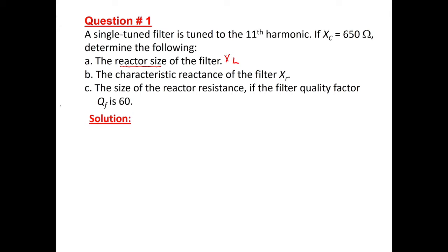We know XC, we know H, therefore XL is equal to XC divided by the harmonic order, which is 11, squared. That will give XL.